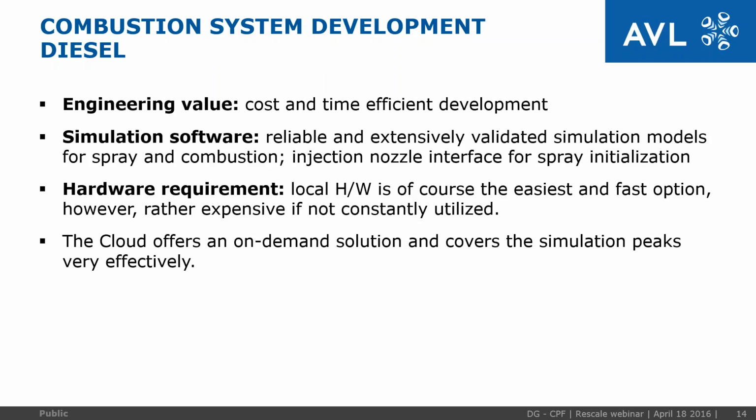AVL Fire is a reliable and extensively validated simulation tool containing models for spray and combustion, as well as injection nozzle interface for spray initialization. In terms of hardware, of course, local hardware is the easiest and the fastest option. However, it could be very expensive if not constantly utilized. Therefore, the cloud, like Rescale's, offers an on-demand solution which covers simulation peaks very effectively.